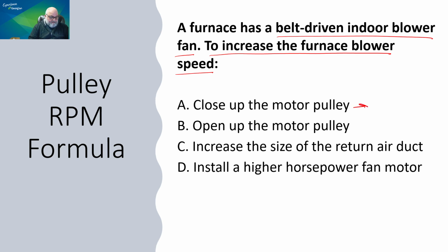So this is increasing the diameter of the motor pulley, and this is decreasing the diameter of the motor pulley. Okay, so you need to do that to increase the furnace blower speed.